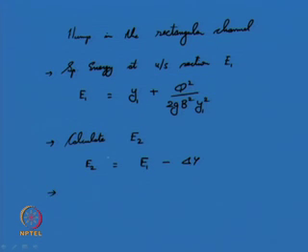Once you compute this, you have to check whether E2 with respect to the critical energy at section 2. For critical energy at section 2, you know this is for a rectangular channel, this is nothing but 3 by 2 into y c. This you have already derived in previous classes.